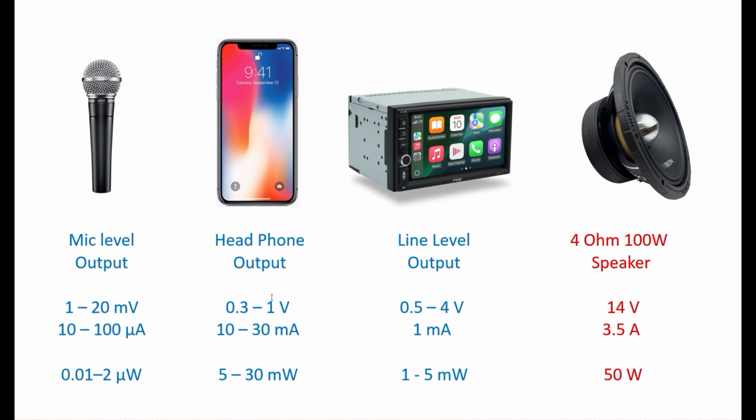And if I look at the power needs of a speaker, and I just use a single speaker, one 4 ohm speaker with 100 watts, pretty small speaker in terms of things, and I want to run it just at half power, I would need 50 watts of power, which would be 14 volts and 3.5 amps, right? So much bigger numbers than any of these little source level signals can ever supply.